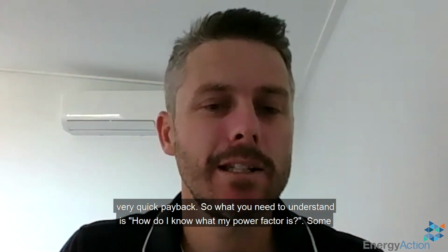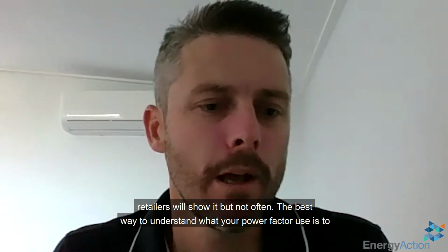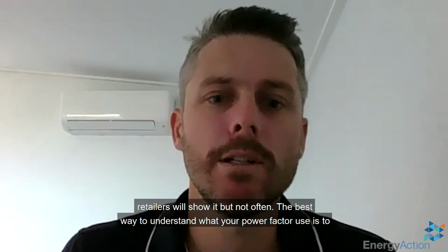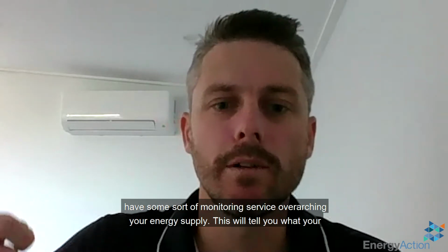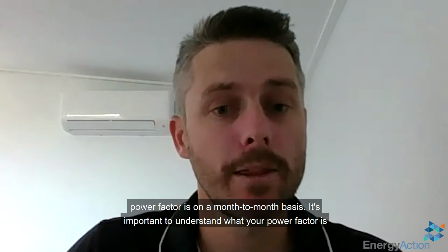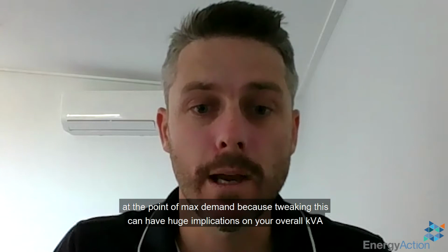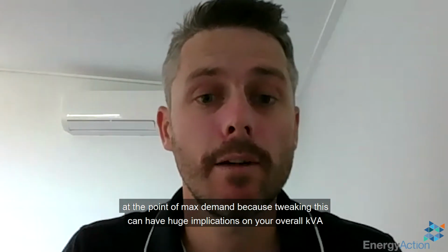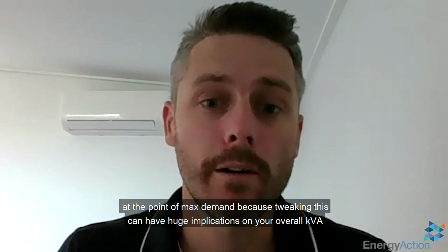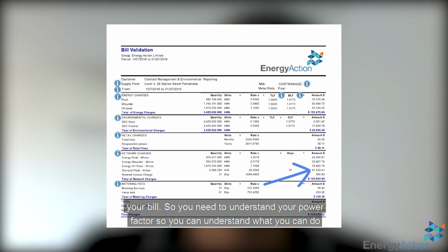So what you need to understand is, how do I know what my power factor is? Some retailers will show it, but not often. The best way to understand what your power factor is, is to have some sort of monitoring service overarching your energy supply. This will tell you what your power factor is on a month-to-month basis. It's important to understand what your power factor is at the point of max demand, because tweaking this can have huge implications on your overall kVA demand charge. In some instances, your kVA demand charge will be the highest individual charge in your bill. So you need to understand your power factor so you can understand what you can do to fix it.